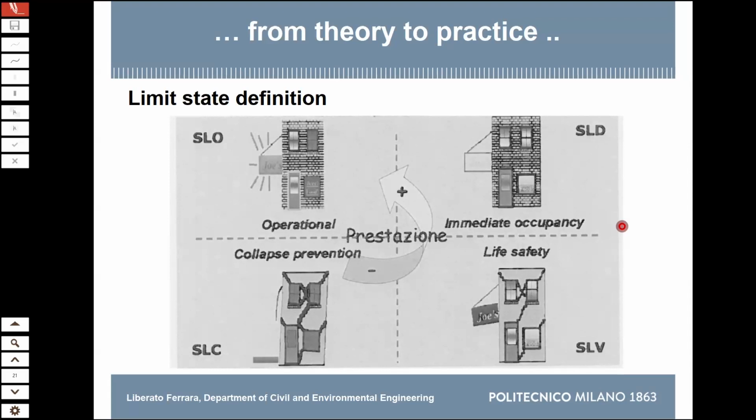And this is the reason for which nowadays, for example, in earthquake regions, San Francisco and so on, for hospitals and other strategic buildings, you use base isolation. Because you can guarantee operational limit state for the structure without base isolation, but then it's very complicated because you should fix your equipment very strongly to avoid that it is damaged. And the equipment that you might have may exceed, from the human point of view, surely, the value of the structure, but also economically speaking, it can be much more valuable than the structure. So this operational limit state, we always consider for very specific strategic structures.